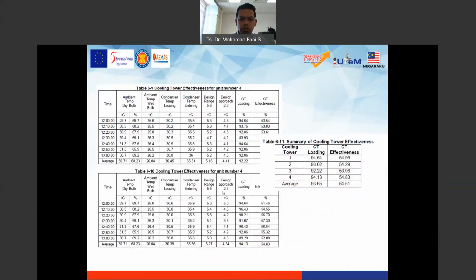Here is the available cooling tower. So we measure all those things and come up with the efficiency, the effectiveness of the system. So for this section 6, remember students, it is all about the measurement and how we can assess the current effectiveness or efficiency. For the chiller, the COP; for the motor, the efficiency; for the cooling tower, the effectiveness, etc. to get to know their loading.